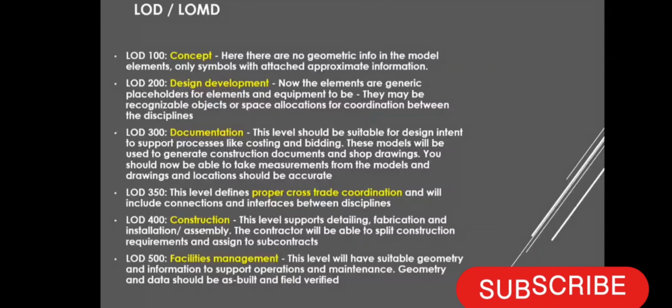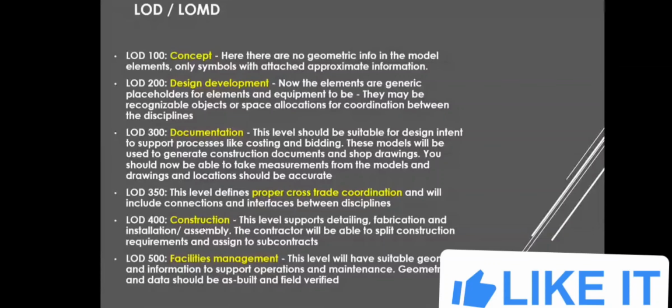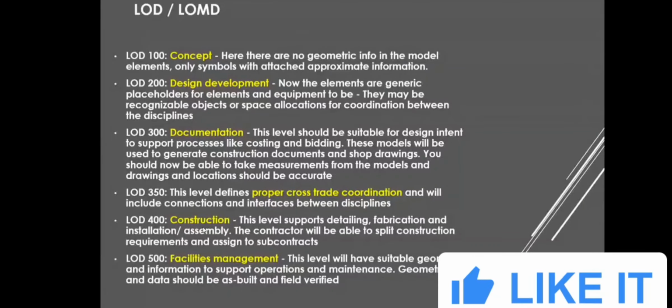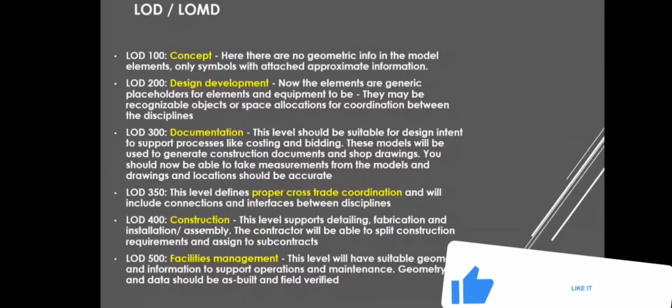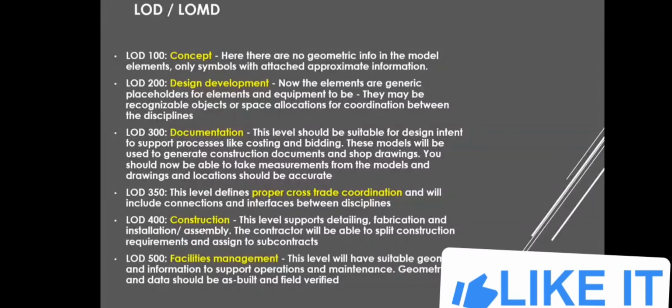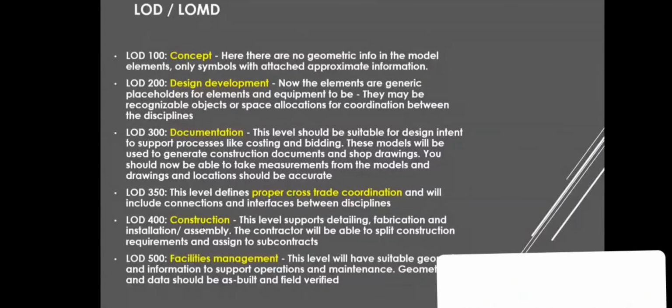Let's say they moved a pipe from your construction model. What you have given in the construction model is correct, but due to some site factors, they have to move the pipe, pipe support, whatever, here and there. If they are making such changes on the site, we have to record those changes back to your digital model. That is called as-built modeling.